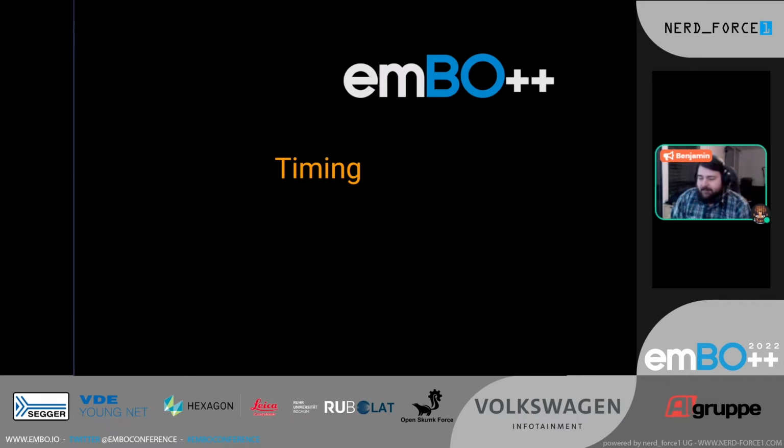Timing is difficult because this is one of the core things you need to figure out for this glitch attack. And we're going to break it into two parts. When do we start the glitch? And how long should the glitch be? Because of course, you can determine, do you want a really short glitch or do you want a really long glitch? Usually you want a really short glitch because